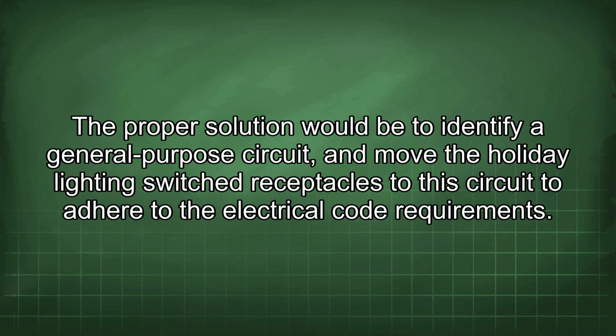The proper solution would be to identify a general-purpose circuit and move the holiday lighting switched receptacles to this circuit to adhere to the electrical code requirements.